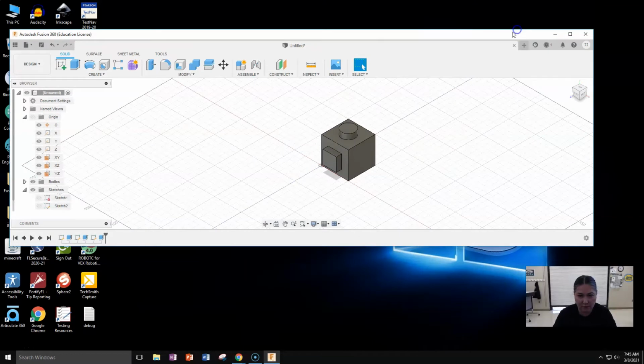So before we go, let's just take a look at the bottom here. The thing I like about Fusion is that it shows your work in the order you did it. So say you've got something complicated, this gets stretched out all along the bottom here, and you can just see what you're looking for and fix that. So it's also over here, but this shows everything.